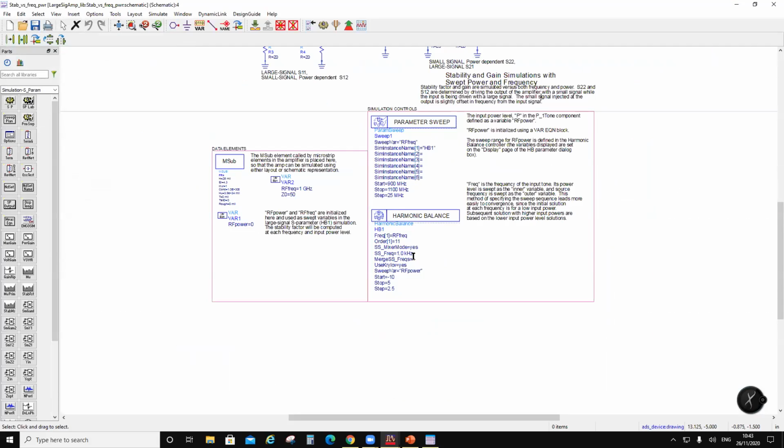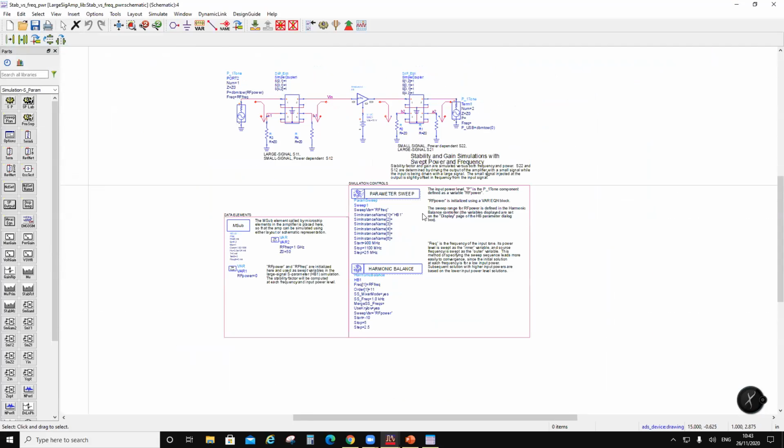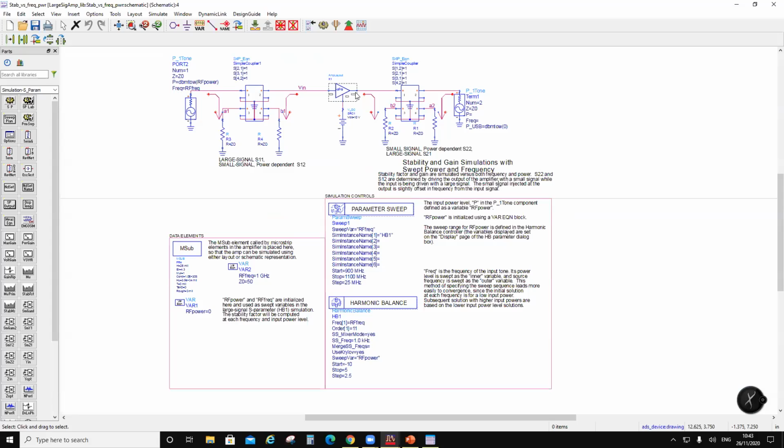And this is the key thing which tells you that load pull is a stupid stuff. Why? Because if you can see the impedances on the output and input, you don't have to do load pull. Only when you don't know the impedances, you do a load pull. When you know the impedances, you do tuning, you don't do load pull. So that's what this bench establishes, that load pull is not required.